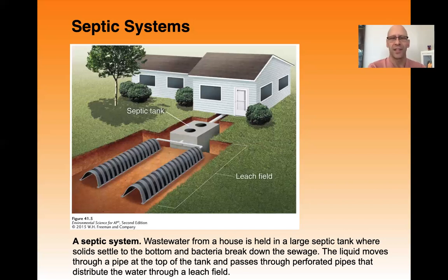These systems can be built anywhere. There was a time when you had to have a proper soil in order to install a septic system, but now they use what's called a mound system. If you're close to bedrock and you don't have enough soil to process your waste, they just bring in soil so you can build a septic system into a mound.